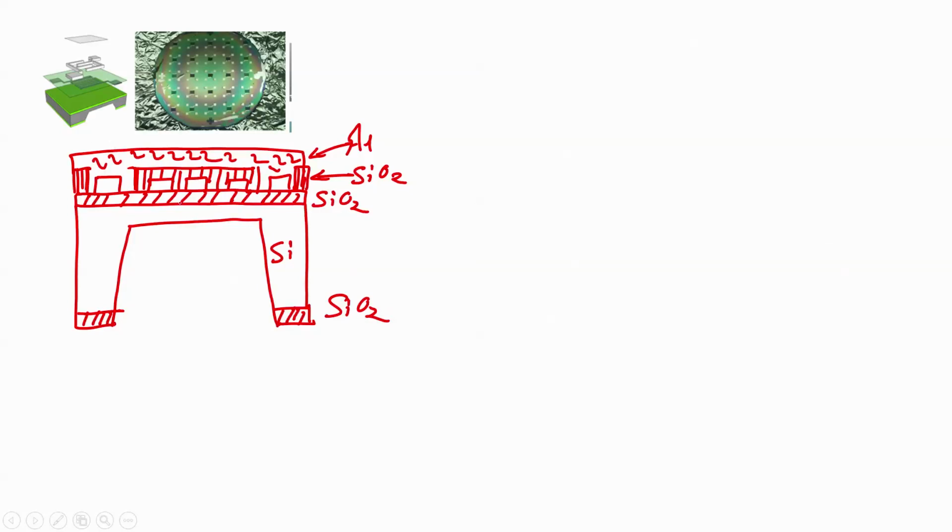Okay. What is the next step? The next step is we have to create interdigitated electrodes on this structure. So, we will deposit a metal. Let us have this pattern for our metal. Our metal is nothing but aluminum. This one would be our SiO2 from PECVD. This is our SiO2 from wet oxidation LPCVD, right, and this is our diaphragm, 100 microns. Now, we want to create interdigitated electrodes.